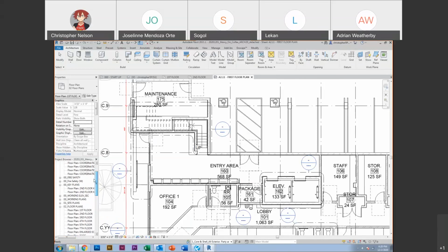But naming everything helps. So for me, with all these different stairs and bathrooms, I can go to 07 vertical circulation. I click the little plus. I have all my levels on my stairs, or at least all the ones I've cut so far in this current model. And I know to look here whenever I'm doing certain parts. So I think that'll help speed you all along.